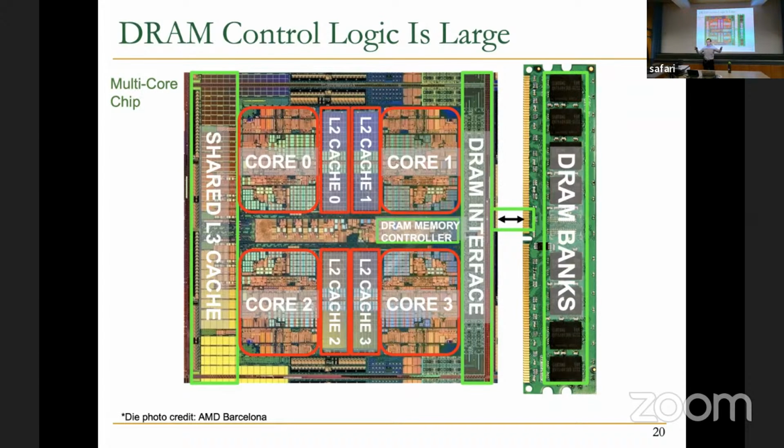It doesn't even do control. That's basically the mindset and history of how things have developed. That's the main reason, basically. Because memory is very cost-centric and emerging technologies were not there, like 3D stacking. The way things have evolved is you had DRAM that was just memory. And if you put a controller inside that die, that would be, first of all, very slow, because the fabrication technology of DRAM is very different from the fabrication technology of logic. When you put logic in there, logic would be slow, very leaky, very high area. So it would go against the cost of DRAM significantly.